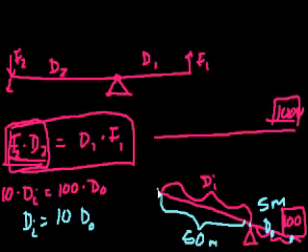And now what would happen? If I design this machine in this way, I will be able to apply 10 newtons here, which is my maximum strength, 10 newtons downwards, and I will lift a 100 Newton object. And now what's the trade-off, though? Nothing just pops out of thin air. The trade-off is that I am going to have to push down for a much longer distance, for actually 10 times the distance, as this object is going to move up. And once again, I know that because the work in has to equal the work out. I can't, through some magical machine...